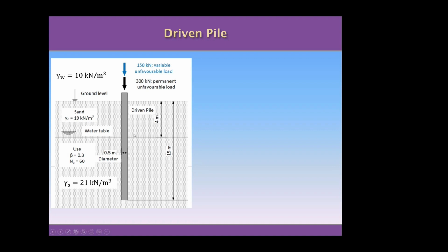What we are doing is analyzing what happened in the ground, in the soil that is in contact with the pile, in terms of friction and bearing capacity. So we are establishing if the soil is able to take the loads that the pile is distributing from the building. This is what we call the capacity of the pile in this case. It's not the capacity of the pile itself, it's the capacity of the soil that is receiving the loads because of the pile.